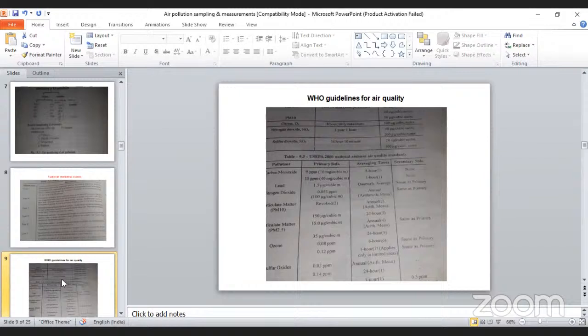And a flow device, like a rotameter, is used to find out how much volume of air is sucked for this sampling. The main characteristics of an ambient air sampling system are collection efficiency, sample stability, recovery, minimal interference, and understanding of the mechanism used. These are what we have discussed, isn't it? All these concepts are basically used for stack sampling.